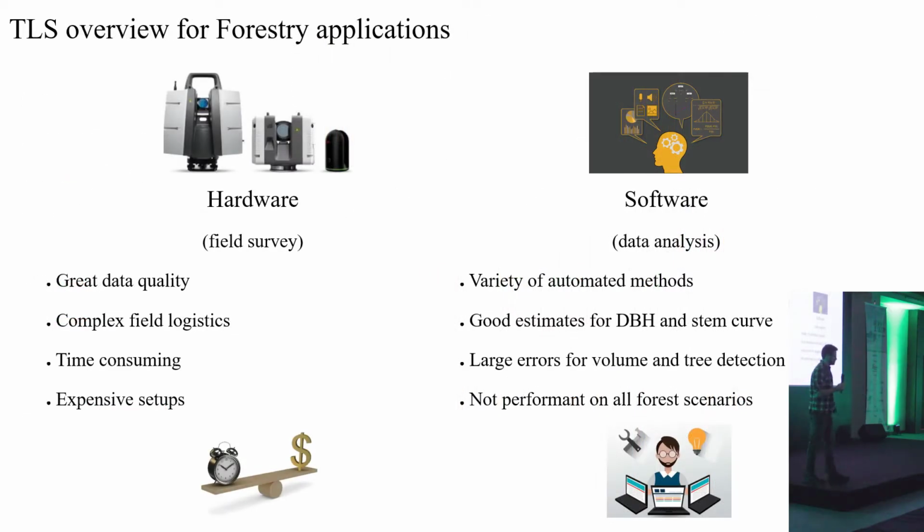And well, just wrapping up the TLS part of the presentation, we can split the TLS in forestry mainly in two realms, which is hardware, more focused on field surveys, and software, more focused on data analysis. So on the hardware side, we have great data quality. We had already 10 years ago great data quality, but the setups were quite complex in terms of field logistics, because you have to install several reflective targets in the field, and depending on the forest you are in, you have to be able to see all the targets from every scanning position, so the logistics have to be very well planned.